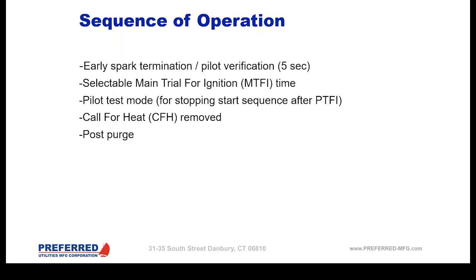Now, if we're doing an installation or some troubleshooting and we want to actually stop this sequence of operation and look at the pilot or adjust the pilot, flame safeguards will have a pilot test mode, and you can turn that switch over so that it stops in the PTFI period so that the pilot can be adjusted.